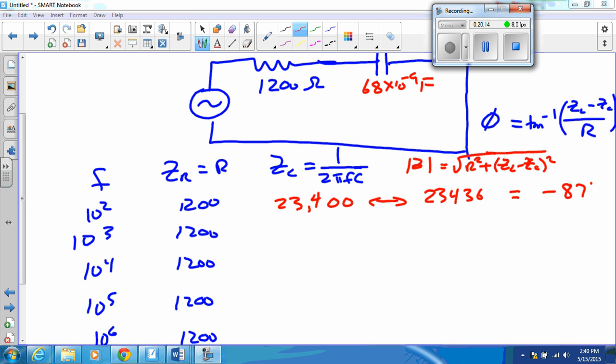All right, I want you to observe the following things. The first is that the voltage across the resistor is basically 0. That's this channel 2 that we're seeing right here. If I look at just channel 2, I'm getting nothing across the resistor. Since V equals IR, that means I'm getting very little current. Why am I getting very little current? Because the impedance of the capacitor is so large.